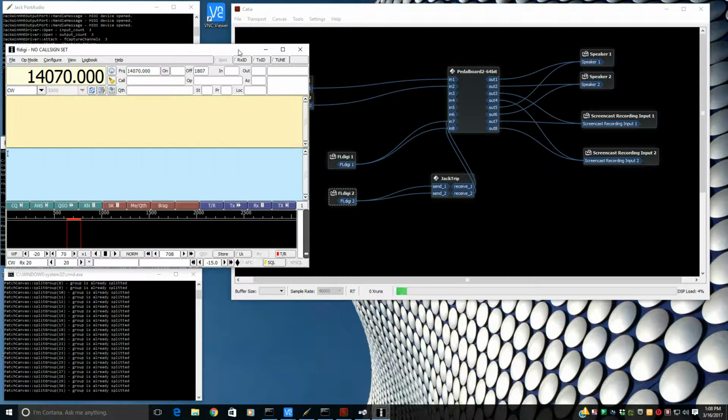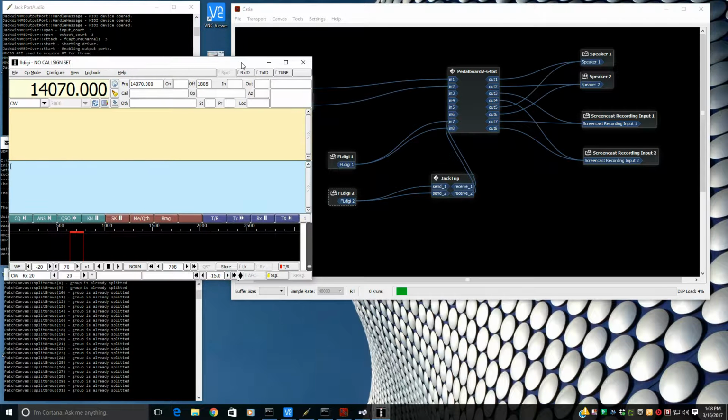to compensate for the audio derived keying circuit, which adds a millisecond or two through the capacitors there that are working to rectify the audio voltage and turn on a transistor to key the rig, which is the output of that transistor is connected to the input of the CW keying jack. It's just a couple dollars worth of parts.